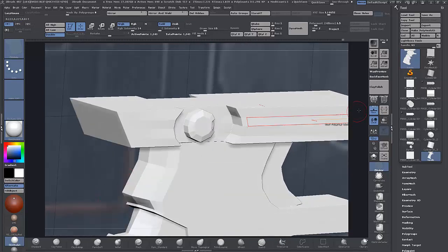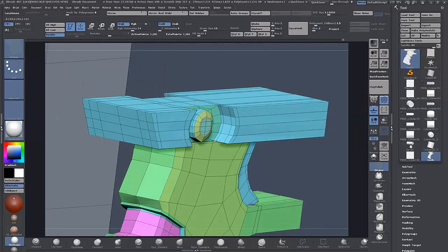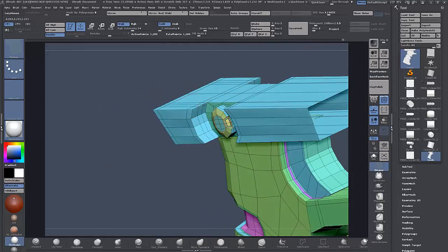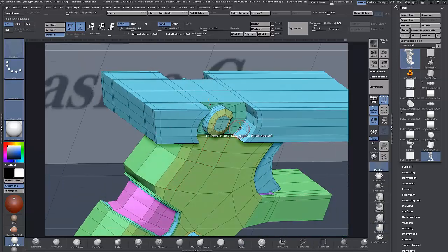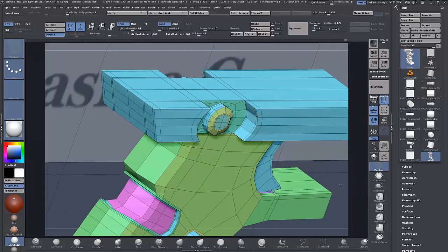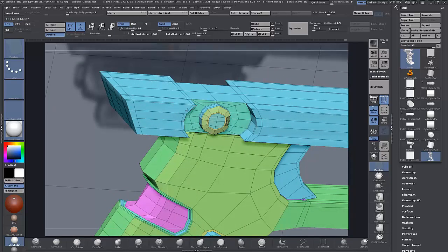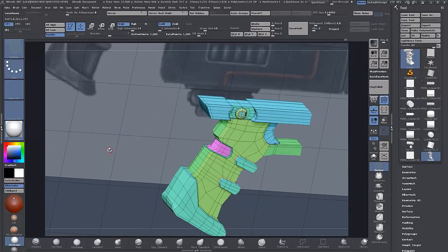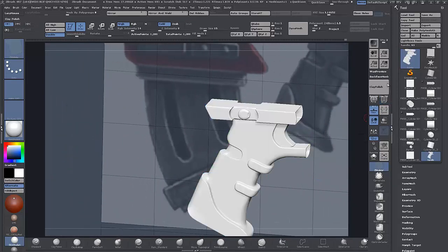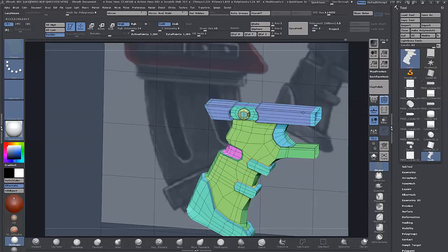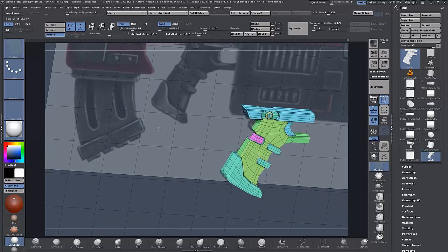And I also want to add an edge loop in here pretty tightly, and here. And what we'll do is I'll just slide these out a bit more, just tighten them up. Maybe the same here, just to tighten them all up. And we're gonna need, sorry, one more in here. Sorry, that was on inset, and inset polygroup, insert edge loop. We'll just insert one there anyway.